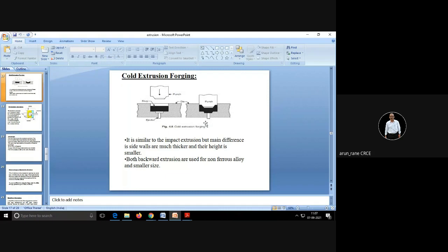And now the punch has gone up. Here, there is no way that the component can be moved up with the punch. It's not possible, isn't it? Because there is no depth and it's a shallow component. So the component will obviously remain in the cavity itself.